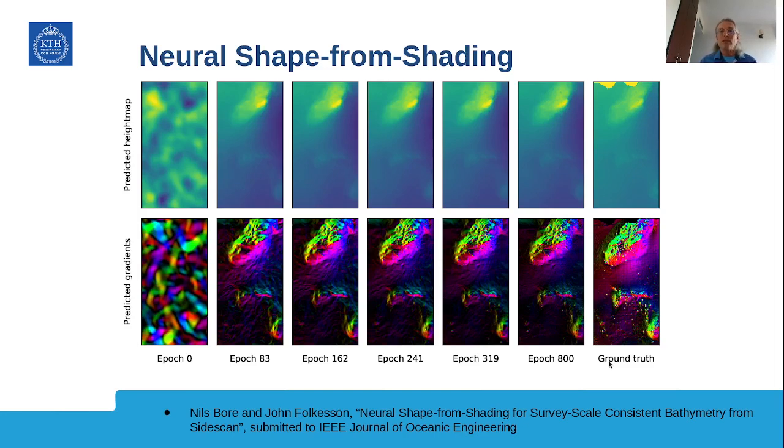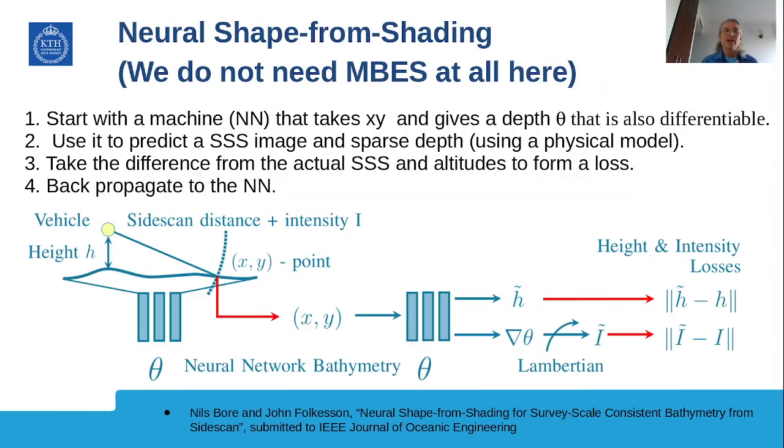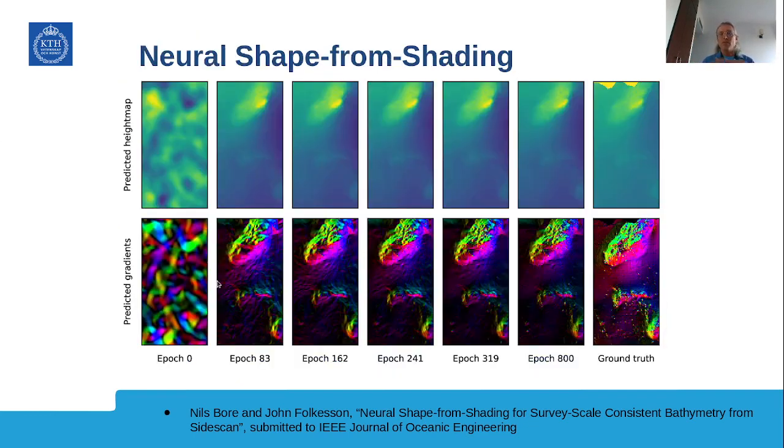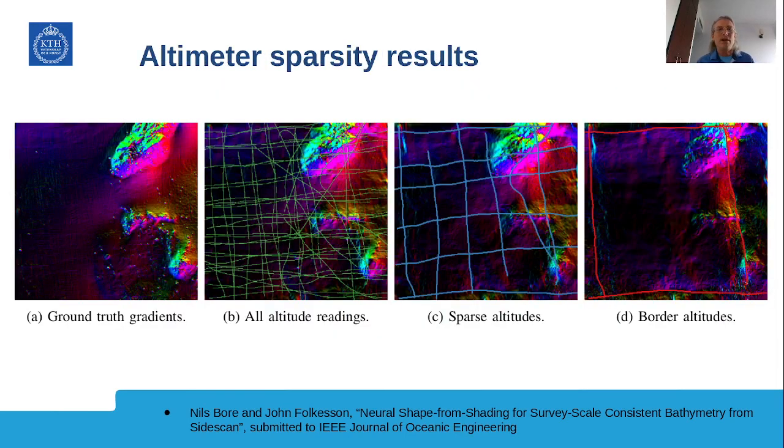bathymetry. And so you can understand now, we automatically take the entire survey, all the lines, whether they overlap or not, and they all get calculated in this relatively complicated step happening up here, which I kind of glossed over, but there's ray tracing and finding intercept points and everything else going on there. That's rather complicated, but due to that, we're going to correctly calculate a consistent picture of the bottom. And you can also look at how the sparse steps affect this.